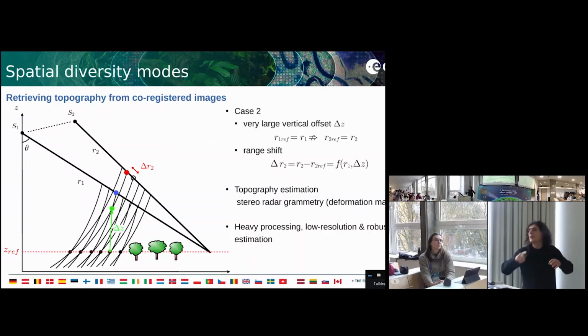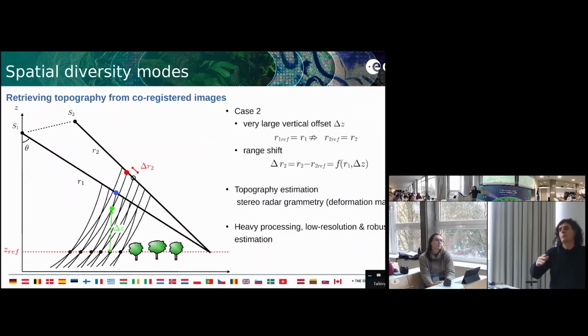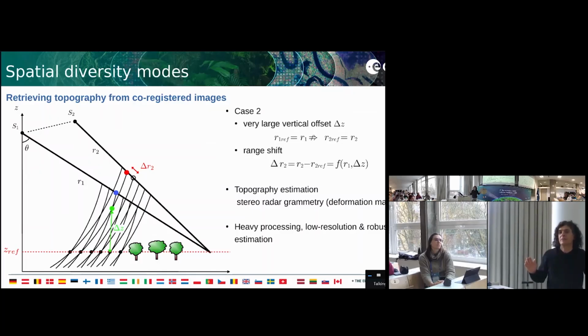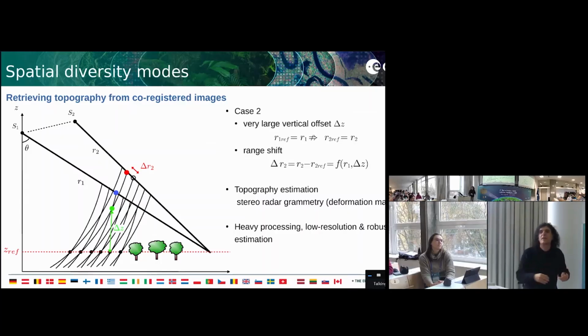So if you follow even a very rough guess of the topography, let's say the Copernicus DTM, which is available to everybody, you will be in the Amazonian forest, you will be maybe a little bit over or within the forest, which is perfect. This is where we want to lie, okay? So we use this as a first guess, and this is what Biomass does, okay? It focuses on this DEM, and after, what you find is relative, or you know that you are relative to this reference geometry, okay?